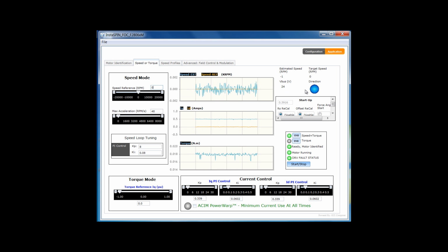So I'm going to go ahead and touch the shaft of the motor here, and it's relatively stiff already. So this isn't too bad of initial tuning, but I'm going to go ahead and make it even stiffer. So I can increase these gains. And now if you try this yourself, you can definitely notice that the controller has gotten stiffer, and I am of course able to move the shaft. This is a small motor, it doesn't provide that much torque, but I'm going to go ahead and triple this value, and it gets very stiff.